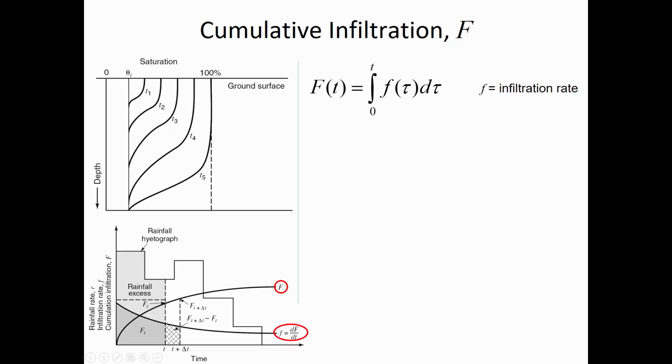And this figure shows both the declining rate of infiltration and the increase in cumulative infiltration, but also it's beginning to plateau and it'll eventually reach some maximum value that it doesn't go above. So look at the rainfall. Initially there was a pretty high rainfall intensity, then the rainfall decreased a little bit, but in each of these cases, the rate of rainfall was greater than the infiltration rate.